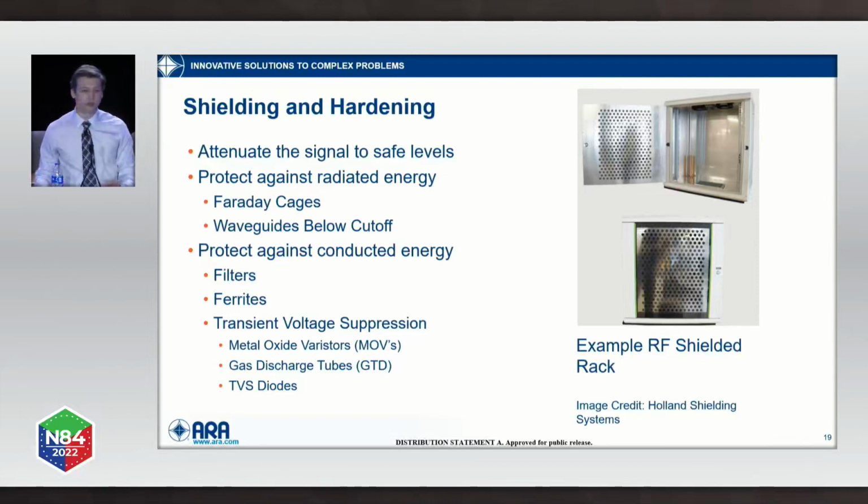What's important to consider with something like a Faraday cage and shielding in general is it's not a situation where every little bit of shielding helps. It's really an all or nothing situation. As soon as there's a small crack in the shield, it's a place where electromagnetic energy can get in and damage your equipment. Your shield might as well not even be there.